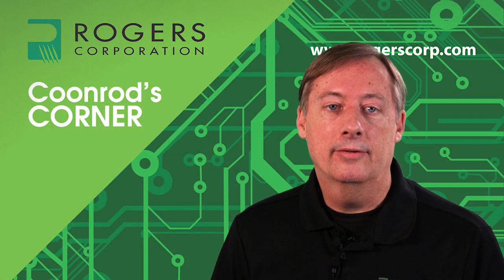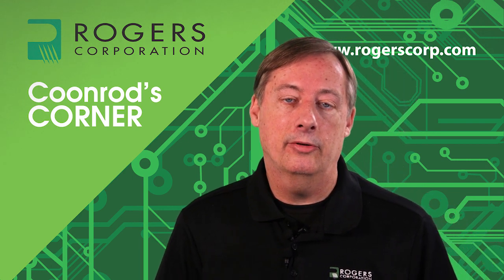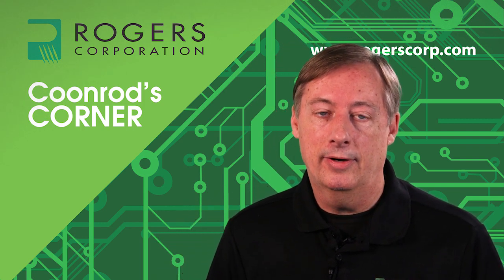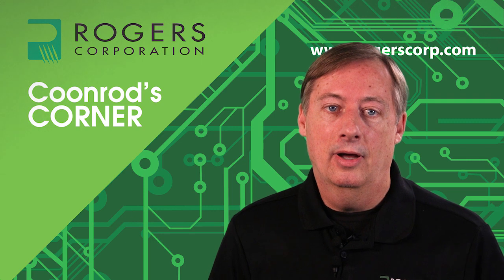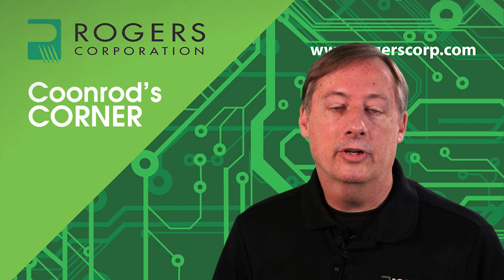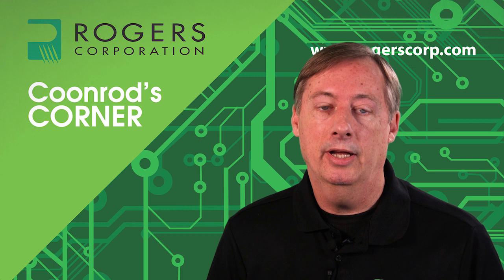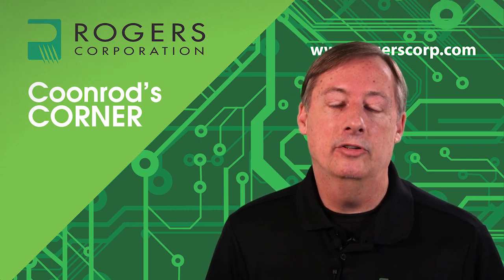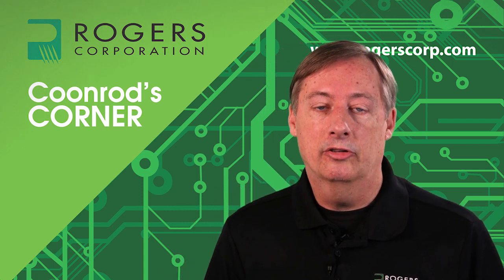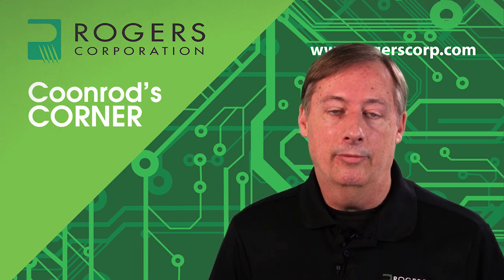In summary, I've talked about antennas for microwave frequencies and millimeter wave frequencies, and the antenna is pretty simple. It's a microstrip series fed patch antenna. And you can see that there are several material properties that I've shown that are very critical to make sure these antennas have the best operation and the best performance. And also there are circuit fabrication issues to consider. I just showed a couple quickly, and one of them is related to circuit etching, but there are many others, and we always invite you to talk to your circuit fabricator about these issues, or you can talk to our Rogers technical support team, which gets heavily involved with circuit fabrication, and that would be very helpful.